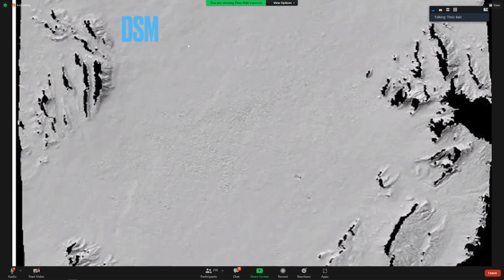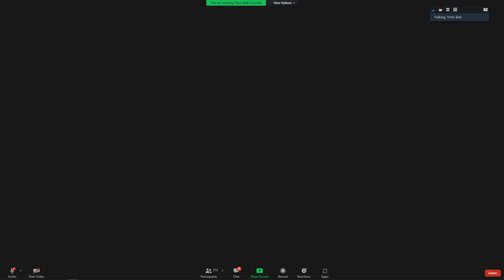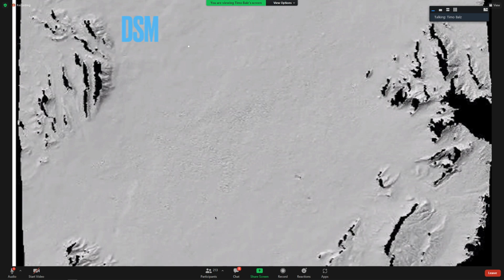Again, it is not uncommon here to have, in such a model, rather large void areas where, for example, in this area we masked out because of the low coherence. You see, we maybe did not get good results on the mountaintop. Maybe there was also foreshortening, layover, or other effects, maybe some shadow effects behind the mountaintop, where we just don't have data. So you will end up with something like that.